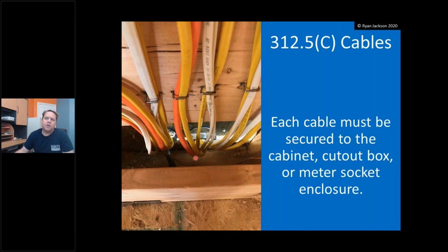Now, how many cables can go through a connector is not something that the NEC tells us. That would be up to the manufacturer of the connector. 334.6 requires that the connector be listed. And once we have listed products, 110.3(B) says that we have to follow the instructions. So look at the instructions and see how many cables you can get through there. I know of one manufacturer that specifies multiple cables. And I would recommend using that because, how many is multiple? More than one. So as many cables as you want, as long as you can tighten it up. That's the one that I would use.